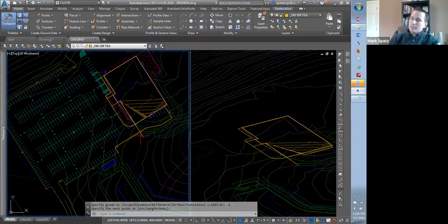Do that same thing, but grab basically where these parking aisles would line up. I'm just going to watch here on the screen, and then I'll let you do this all in one shot. So we're going to grab this edge, come down at 2%. If you're in the middle of that, just pause here for a second and look back up.